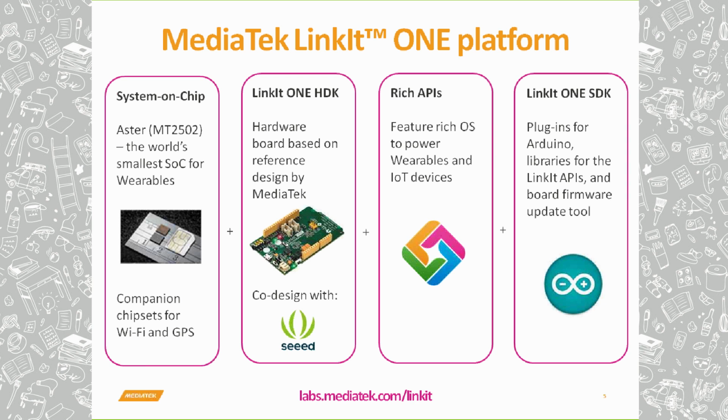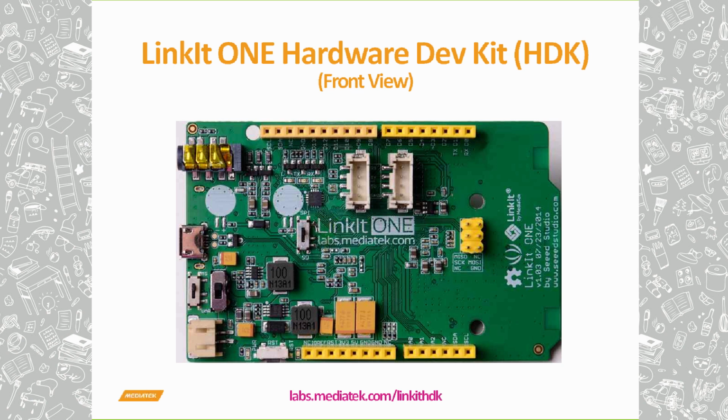So this is the board, as you see from the front. You might recognize that it's very similar to an Arduino Uno in terms of the pin layout, which makes it compatible to other Arduino shields. So if you already have shields, it will be compatible to it. But let's have a look at the individual components. So at the top, you have the GPIOs. In total, you have 16 digital input-output pins. At the bottom right, you see the analog ones and also some extra GPIOs. And then you have the power output at the bottom left. So very similar to other Arduino boards.